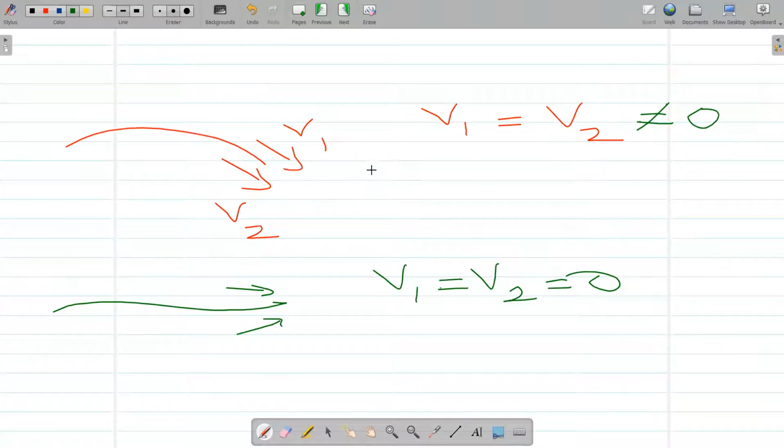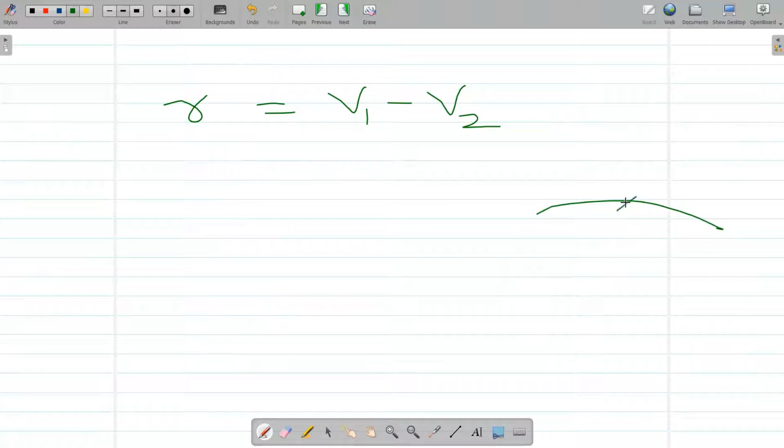And we also know, not from the Kutta condition, that the strength of the vortex sheet at any given location, gamma, is given by the difference in velocity between the top and the bottom. That is, if you have a vortex sheet, the strength at a particular location is given by, let's say v1 is the velocity at the top and v2 is the velocity at the bottom. So v1 minus v2 gives me the strength of the vortex sheet at this particular location. Let me call it x.